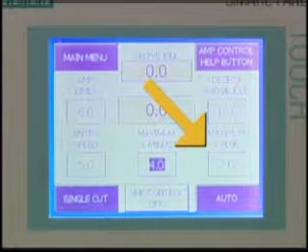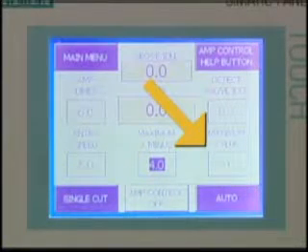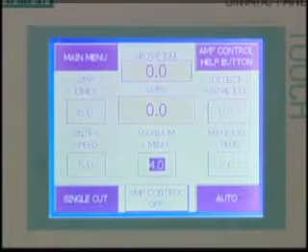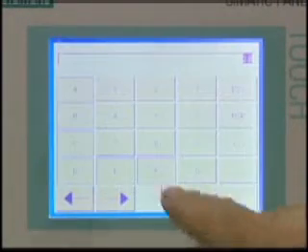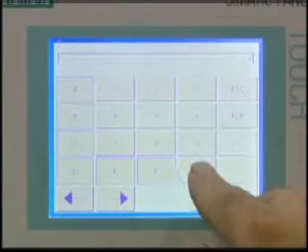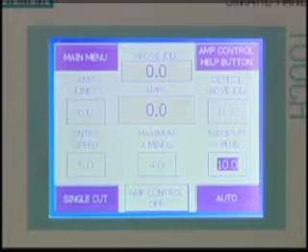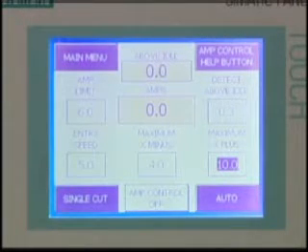Enter the x plus maximum speed. This is a limit placed on the speed of the x plus movement, whether or not the load amp increase has been reached. It's typically set between 10 and 12 feet per minute. The actual speed of the arbor moving across the cutting surface will be limited to this number even if the amp limits are not engaged, for example, as the saw passes out of the stone.